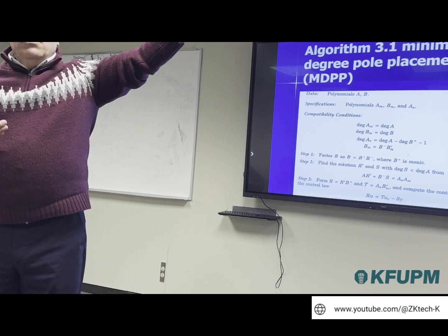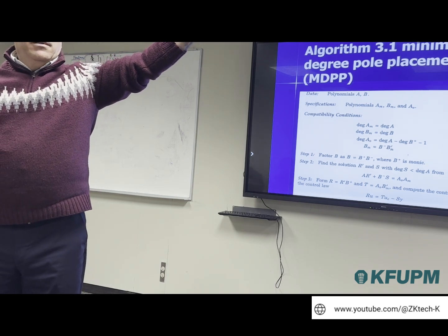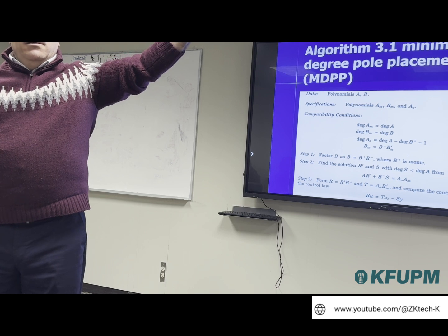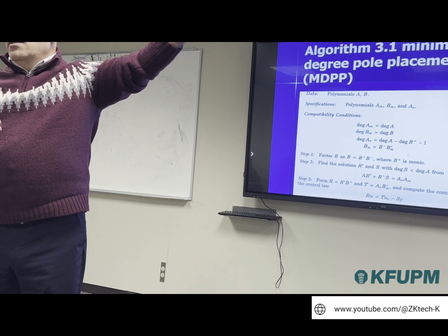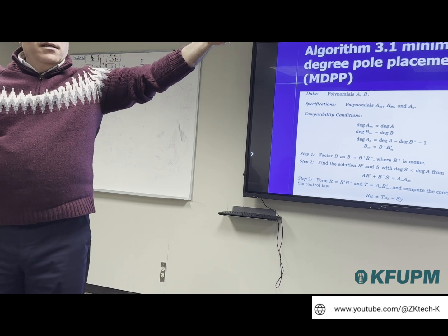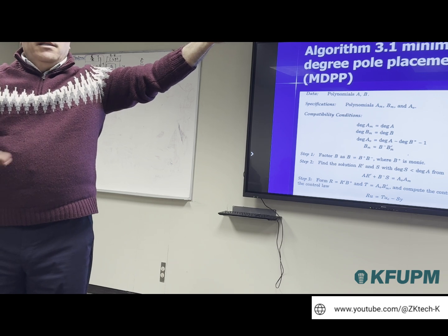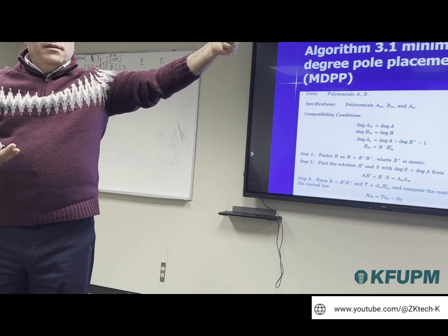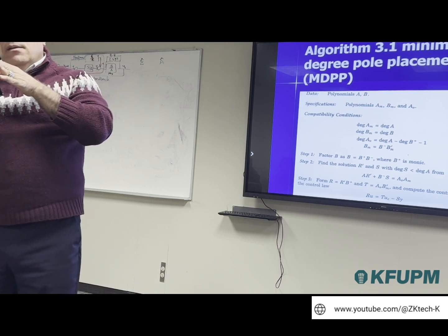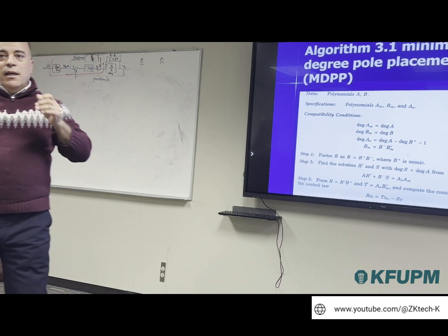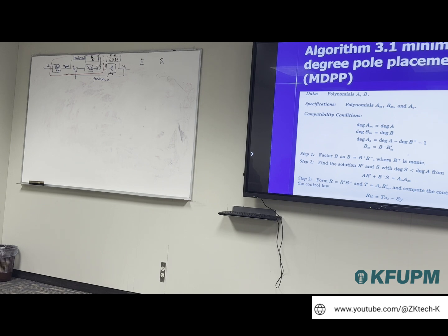So if you are going to start with any initial value of parameter theta, then you need to probably make a condition. Unless the error is less than something, you should keep always at the same frequency as the controller. Once the error is within a reasonable limit, then you can relax the estimation. Is it clear what I said? It makes sense?